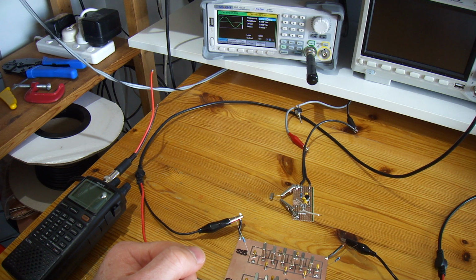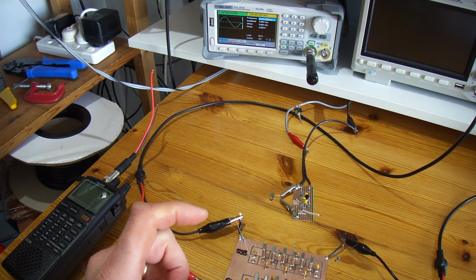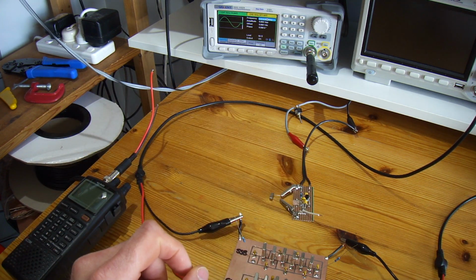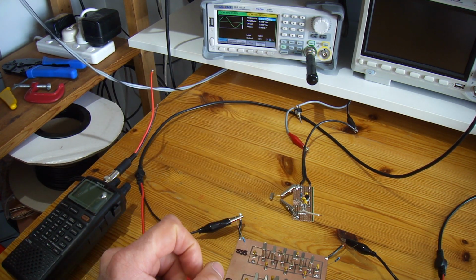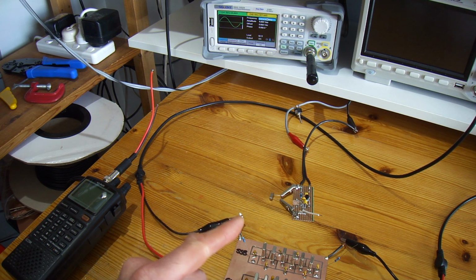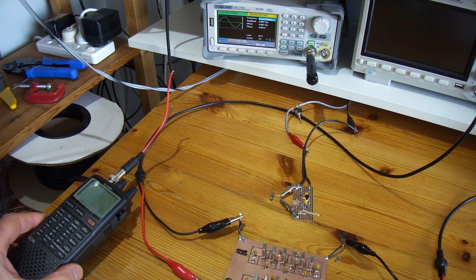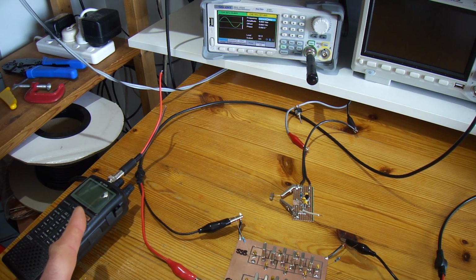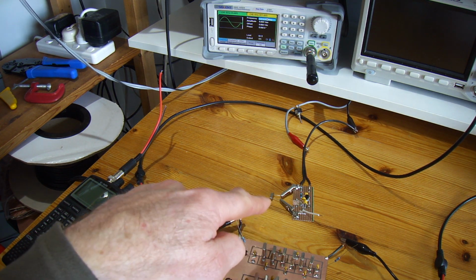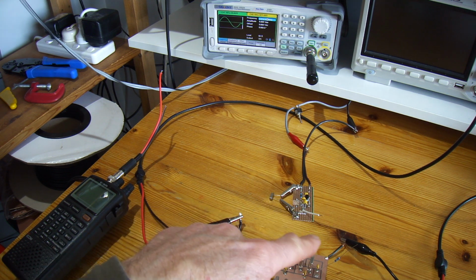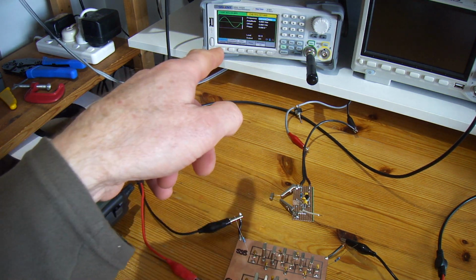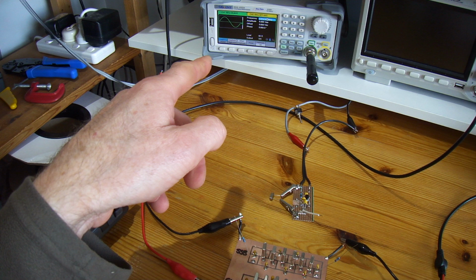I started with the 4.95 ones, and to measure their frequency and then basically set them aside, and I put them into little bins of 5 Hertz. The way I did that was to use an approach which I've used before, which has certainly worked well, which I'll look at in a sec, and that's to use a simple communications receiver to receive not only the crystal filter and what RF it's radiating, but also at exactly the same time the output of a signal generator